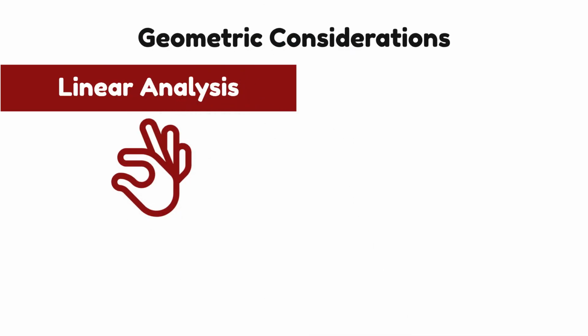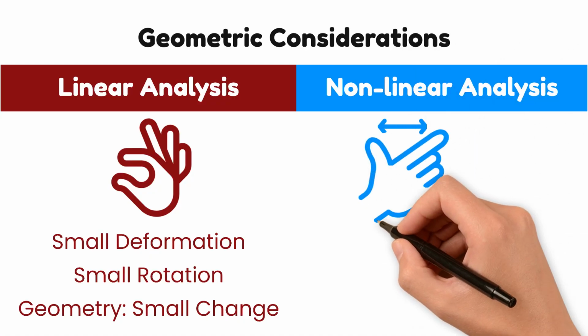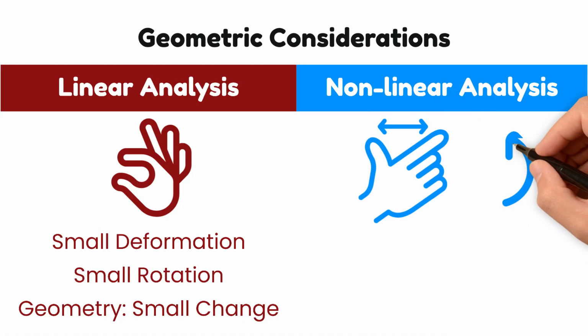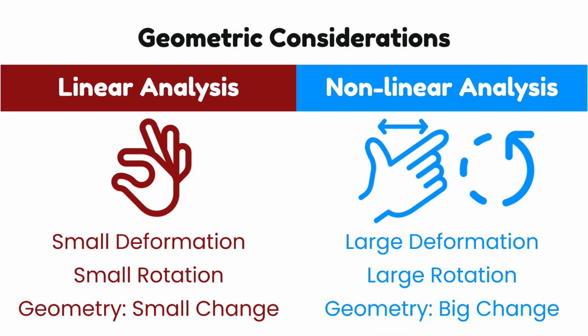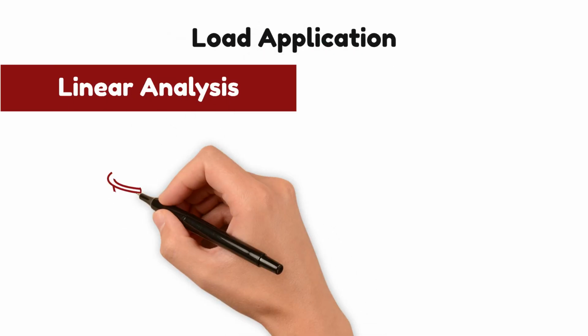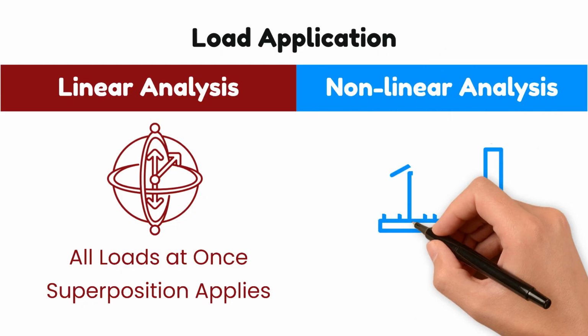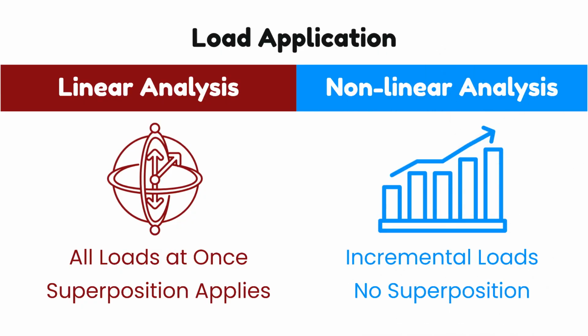Only small deformations and tiny rotations. But in nonlinear analysis, the geometry can change drastically. Think large bends, twists, or displacements where the updated shape actually affects the next step of your solution. In linear analysis, all the loads are applied at once, and since everything scales proportionally, the principle of superposition applies. But in nonlinear analysis, loads are applied incrementally, step by step. Each load step changes the stiffness and response, so you can't just add results together anymore.